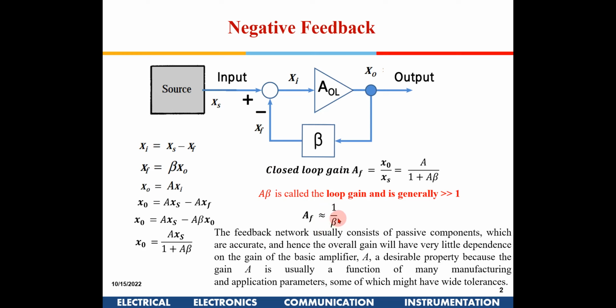But the advantage here is, when we talk about the gain of an amplifier, it is like gm into R0. For a normal common source amplifier or a differential amplifier, all these gm, R0 come from active devices and are dependent on temperature, process variation and voltage variation, so they are not very stable.